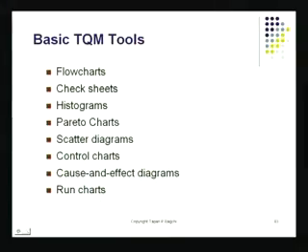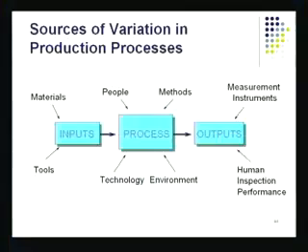So, control charts have a different function. They try to help you control a process, to keep accuracy in control and to keep precision in control. 2 objectives. And what does the run chart do? It just tries to make sure your production is within specification. That's what the run chart will do. So there are different applications. So a process is there, there is input going on, and all these different factors, they might be impacting your process. So your sources of variation is something that we do not like.